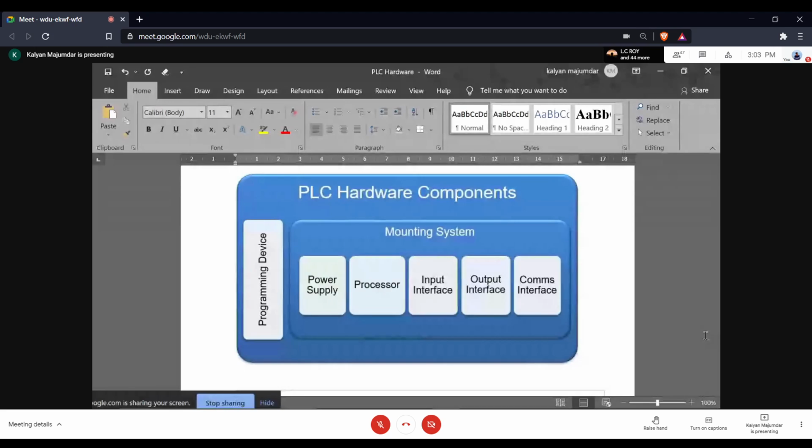But if you want to have a display, if you want to have a graphic user interface, if you want to have a visualization, typically it was HMI. Normally, PLCs come with an HMI so that the user can give their inputs and you can observe the status of the system. You already know you've used visualization quite extensively. So where do I generate this particular visualization if I don't have a display device? Here you've been doing everything within a computer. But when you are using that program in a PLC, the PLC by default does not come with a display. So you need to connect a display to this particular PLC. How do you connect? Again, you require a separate display device which communicates with the PLC. So you require some kind of a communication interface on the PLC and on the display device. Again, as of today, that's an Ethernet interface.